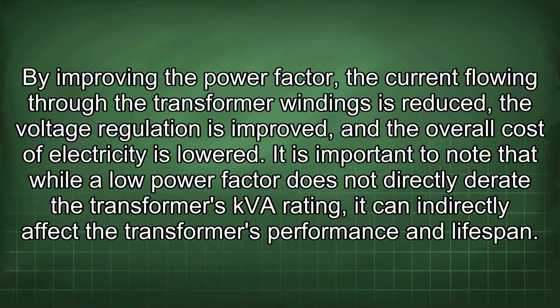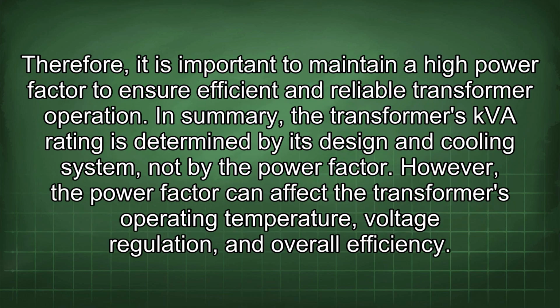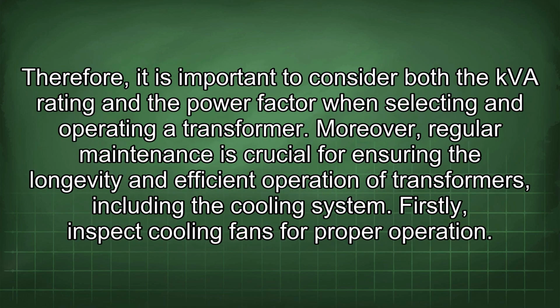It is important to note that while a low power factor does not directly affect the transformer's KVA rating, it can indirectly affect the transformer's performance and lifespan. Therefore, it is important to maintain a high power factor to ensure efficient and reliable transformer operation. In summary, the transformer's KVA rating is determined by its design and cooling system, not by the power factor. However, the power factor can affect the transformer's operating temperature, voltage regulation, and overall efficiency. Therefore, it is important to consider both the KVA rating and the power factor when selecting and operating a transformer.